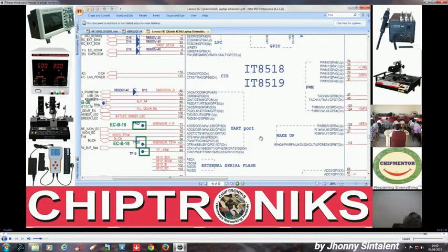The processor can directly communicate with the controller present inside the desktop keyboard by the address 60H. That is, if we want to read the information from the 8048 microcontroller present inside the desktop keyboard, the CPU